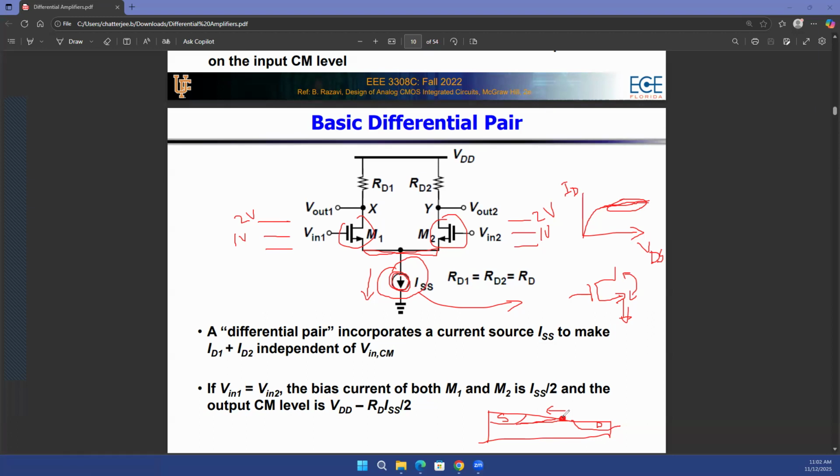So if the length of the transistor is large, any kind of channel length modulation effect will be very small as compared to the original length. So how does it matter if I change a micrometer in a mile-long transistor? If I change a micrometer in a 10 micrometer long transistor, then it matters. If I change a micrometer in a 100 micrometer long transistor, it matters less. Right? It's just 1%.